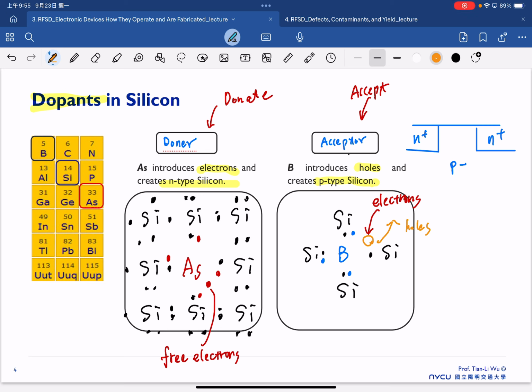So finally we found that the amazing part of the semiconductor material is that we are able to dope different kinds of species. We are able to manipulate their doping concentration. In the end, we can manipulate their conductivity and resistivity. Usually the plus here means heavy doping, which means this is a place where we have very high doping. And the minus here means we have light doping.